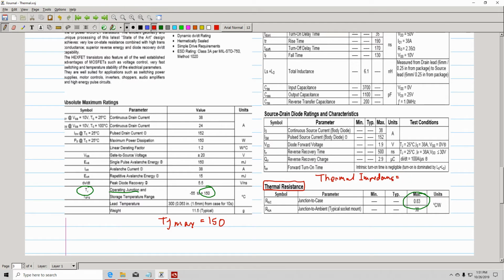In other words, you have the thermal resistance, and then you have, remember, the capacitance, the thermal mass, so that would be kind of like the imaginary part. In this case, R theta is the resistance. This is the number that we want to use, especially if we're going to mount it, let's say, to another heatsink or to a board. So that's the number.